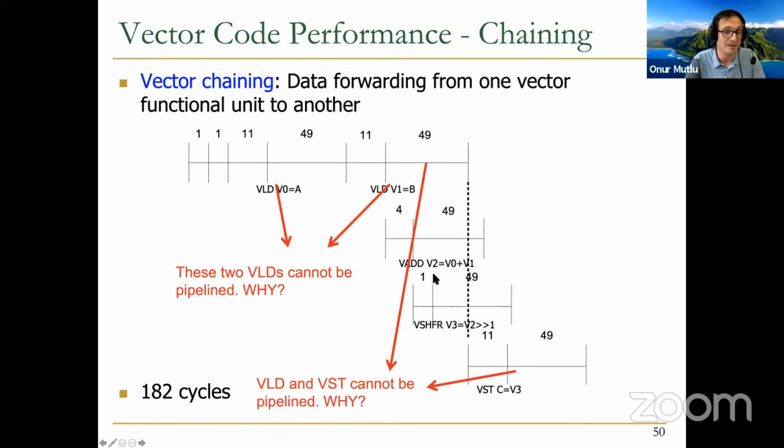This load and store cannot be pipelined because we have only one address generator and one port per memory bank. So what is the solution? Basically, add more ports, so that we can start to access different addresses in the same bank concurrently. This requires 2 address generators concurrently, maybe 3, right? If you want to do multiple, 3, more than 3. And we're going to do 3 actually.